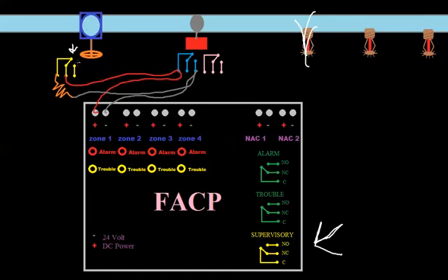But let's say that this was closed a little bit, enough to open up this circuit. Well, if we had gone here first and then went to our water flow, once that circuit opens, we're never going to get our alarm. So we always need to go to our water flow first so that it'll short out and then come out and go to the valve tamper, and we put our resistor in series. Hopefully that's an easy enough idea.